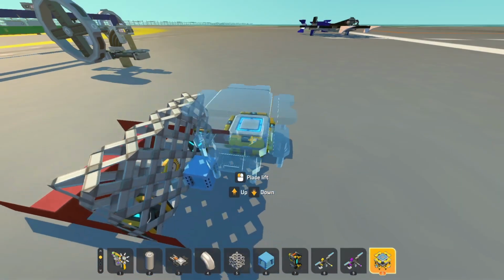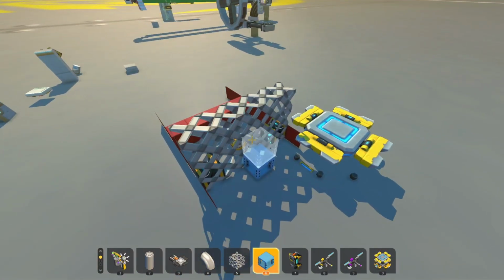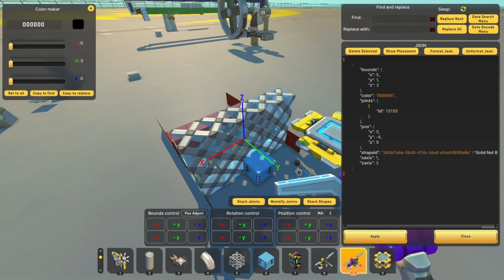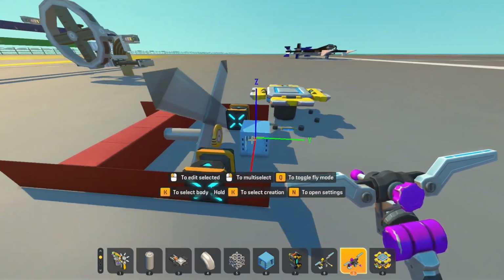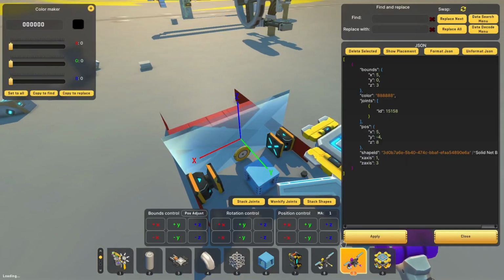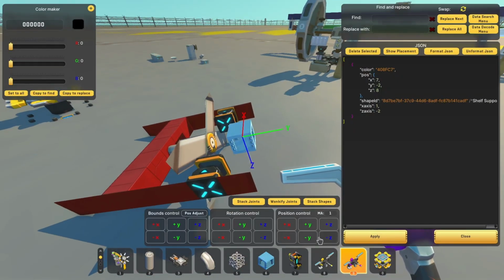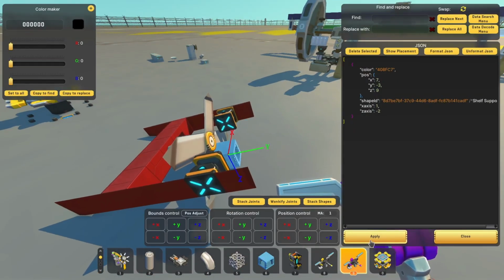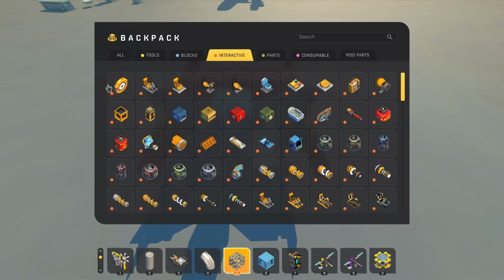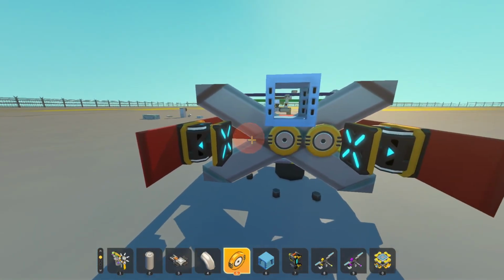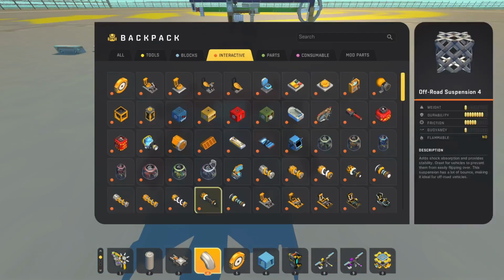So what I'm going to do here, I'm going to place a part. If you want to be really easy about it, you can work with parts, but you don't want to end up subdividing the block you're working with. So now these are still connected, but they haven't updated. So I'm going to keep moving this into position. And yeah, just move this around. So now they're connected. So then I can go ahead and place down the bearings that will be on the flywheel. These will go here.